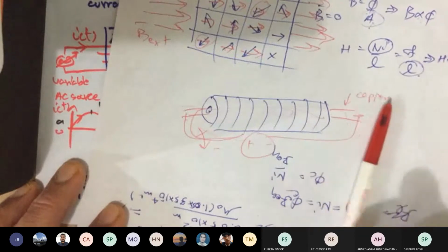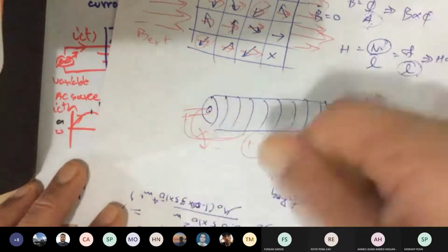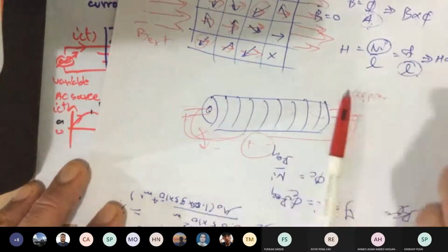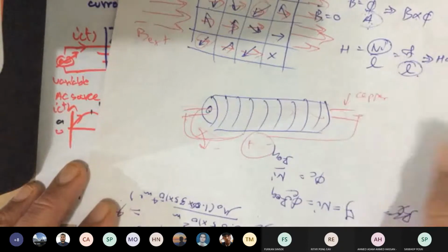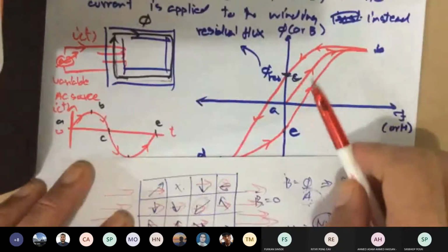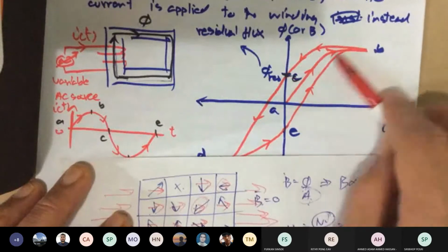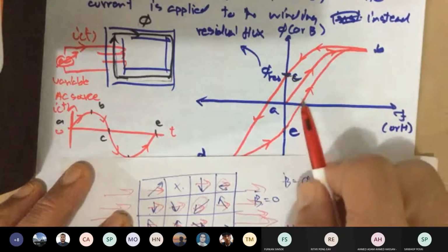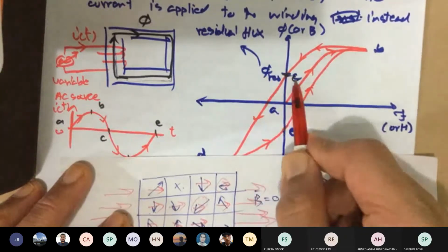Or you can do it at home using paper clips. Go to your refrigerator and wipe them on the door of the refrigerator, maybe a few times. Those paper clips become magnetized. And that's what you are doing. You apply an external field from the permanent magnet on the refrigerator door to your paper clips. When you take them off the fridge door, it leaves some residual flux in the paper clips.